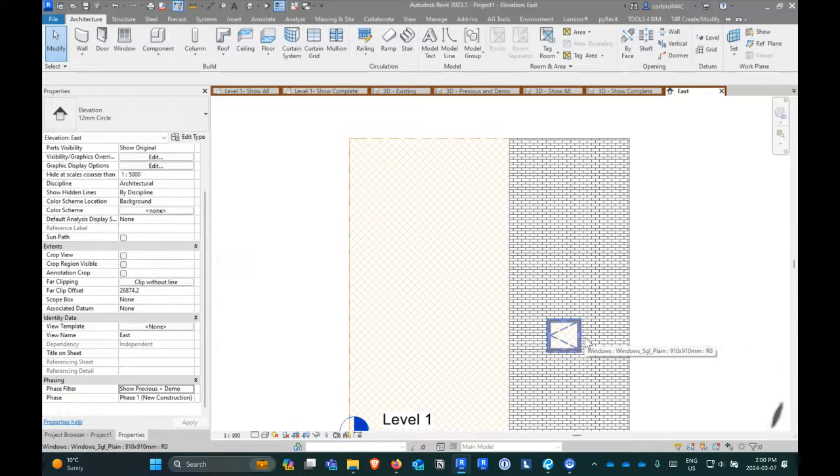So I think this is something that we've worked on quite a bit because renovation projects are really hard to document. So we model a little bit differently. We model our walls broken apart a little bit. So we have an interior layer and an exterior layer, and we actually model two walls everywhere. And so when we're working on renovation projects, sometimes we're actually just demoing the exterior finish, and then we're adding an addition on but keeping that wall there. So that's something else we do.